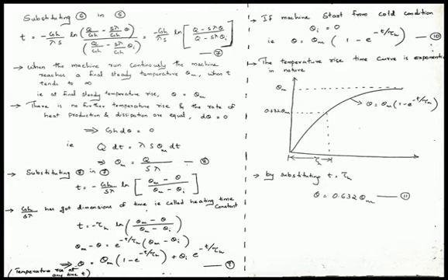Now modifying the heat balance equation accordingly, you will get the expression q dt is equal to lambda s theta m dt, because at the final steady state condition, the temperature rise over the ambient medium is indicated as theta m. From this you can obtain the expression for the final steady state temperature rise over the ambient medium, that is theta m, which is equal to q by s lambda. You must be familiar with this relation, because it is required for solving the problem.